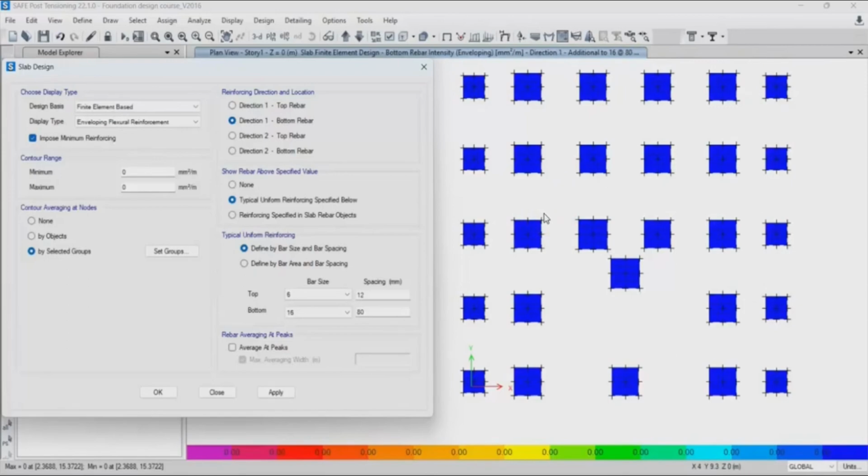So now you might ask the question, why are we placing a 50% threshold? I already explained this: first of all, because of the overlapping excavation, right? Because if you have, let's say, 20 different isolated footings, and you want to dig each of these, let's say the thickness is 1.5 meter deep, you need to bring an excavator to dig at each footing. Now, if these footings are so close to each other and you try to dig out the soil from the ground,